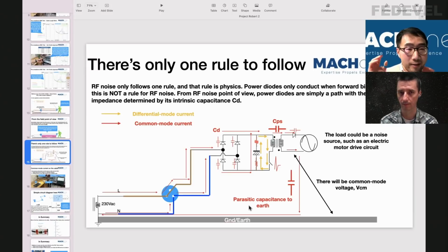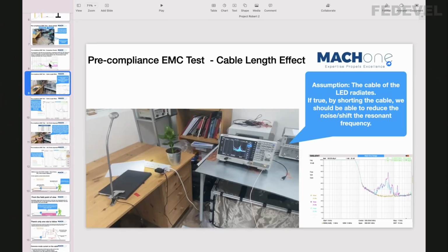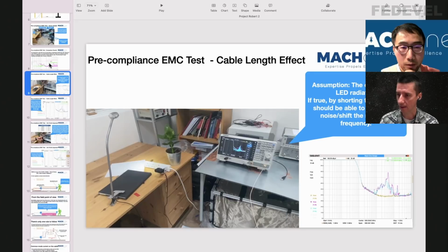Okay. So the next step really is to open up the product and see what's inside, and whether we can fix the problem inside. So we are going to have a closer look at the lamp, and how it is connected. I can see we were talking about this. There is an LED directly in the lamp, then there is a long cable connected to an adapter, and the adapter is connected to the mains. So basically the LED is powered with low voltage DC from the adapter, correct?